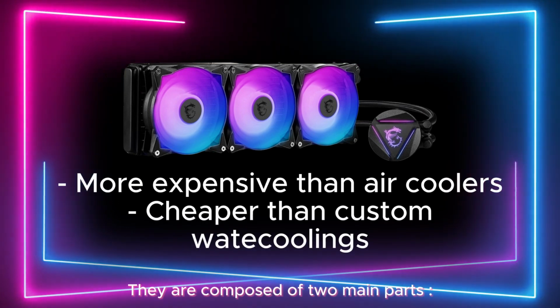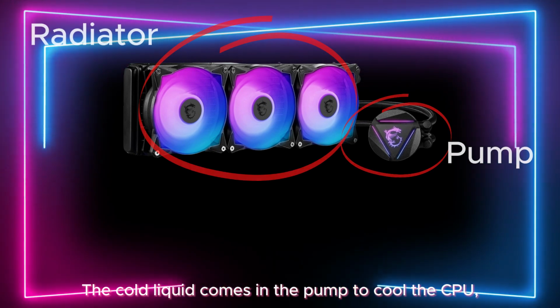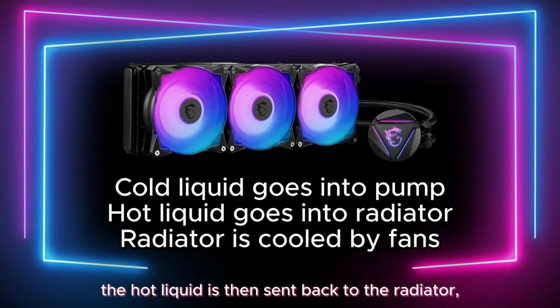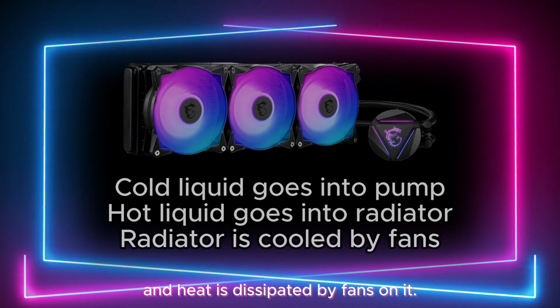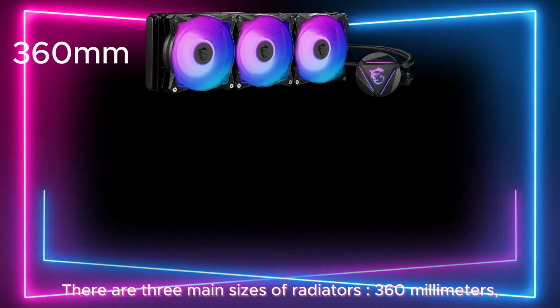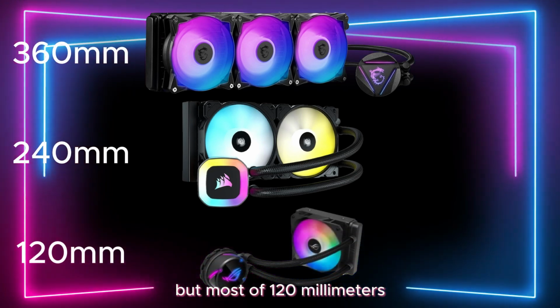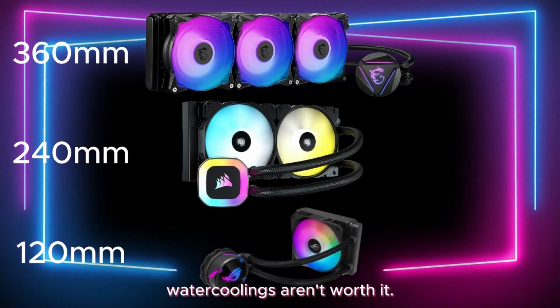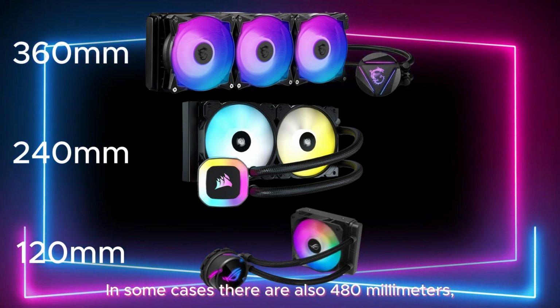They are composed of two main parts, the radiator and the pump. The cold liquid comes into the pump to cool the CPU, the hot liquid is then sent back to the radiator and heat is dissipated by fans on it. There are three main sizes of radiators, 360mm, 240mm and 120mm, but most 120mm water coolings aren't worth it. In some cases there are also 480mm, but it's quite rare.